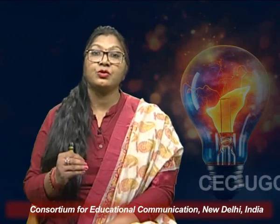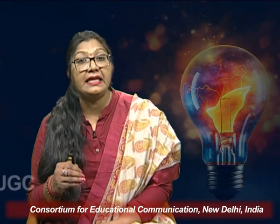If we talk about the difference between the conventional incandescent bulb and the fluorescent bulb, conventional incandescent light bulbs also emit a good bit of ultraviolet light, but they do not convert any of it to visible light. Consequently, a lot of the energy used to power an incandescent lamp is wasted. But a fluorescent lamp puts this invisible light to work, which is not possible in the conventional incandescent light, and so is more efficient.